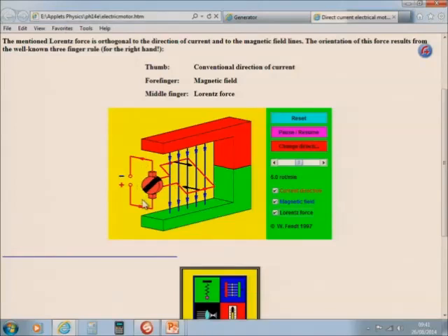Let us just recap on that. Why split rings? The split ring will change every 180 degrees the direction of current through the armature. That will result in a force being in the same direction for the whole 360-degree turn, which will give me continuous motion. All right. Now, where will we find applications all around us every day?